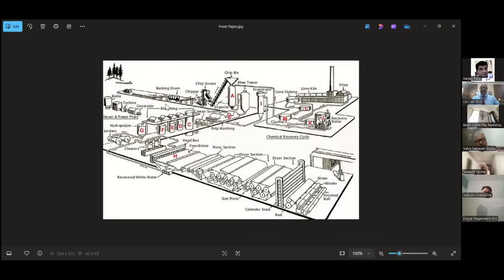The wood pulp is normally in gray and dark gray color. So our paper requirement is white color. So again we are adding the bleaching, normally clay and caustic soda, which absorb the unwanted pigments, brown or dark brown color pigments, in the bleaching process. Again, after the bleaching process we are also adding some additives and other chemicals which give strength to the paper.